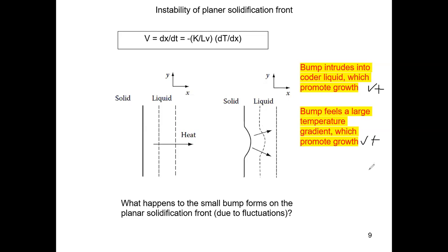But what is the negative effect? What is the bad thing about the bumpy surface? It has a curvature, right? If it's a bumpy surface, it has to have some curvature compared to the flat interface. And we know that whenever you have a curvature, you're using energy, right? You're using the overall free energy reduction to overcome some extra surface energy. Does this make sense to everyone?